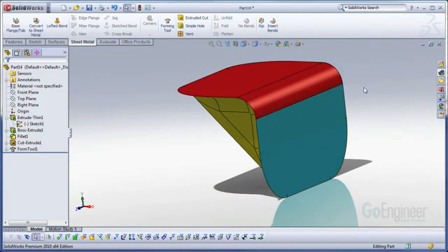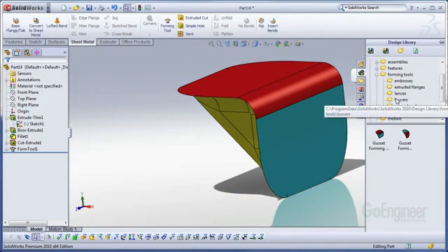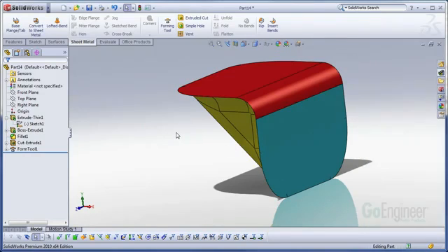At this point you save this file and you move it into your sheet metal forming tools directory. In this case I've created a cross bends folder. I've put a gusset forming tool into it. It's ready to go. It's ready to be pulled out onto a sheet metal object.